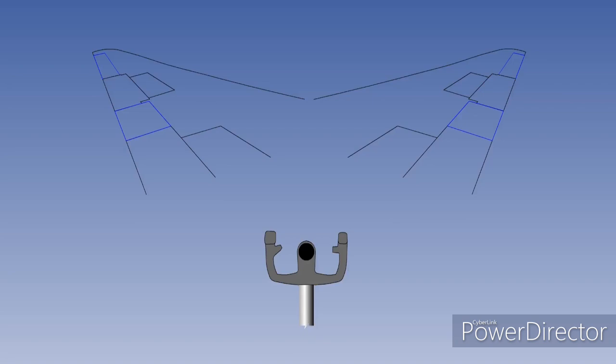You have previously been shown that flaps are fitted to the trailing edge of the wing, and you have now been shown that ailerons also occupy part of the wing trailing edge. The resulting reduction in flap area reduces the efficiency of the flaps. On large, modern high-speed jet transport aircraft, this reduction in flap area is a significant disadvantage, so design changes have been made to make the ailerons also work as flaps. Hence the name flaperons.